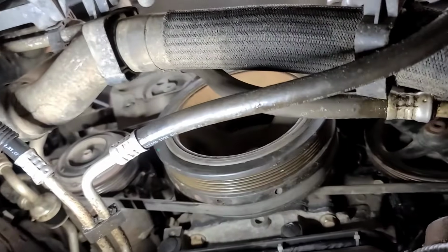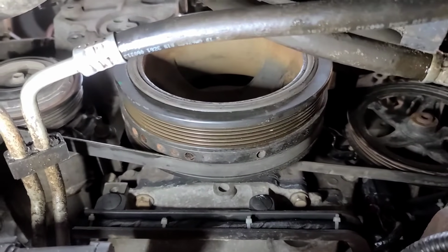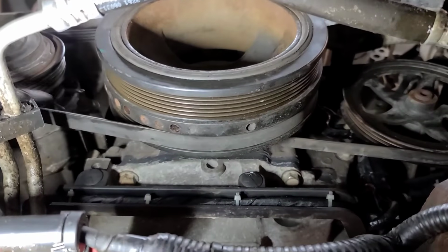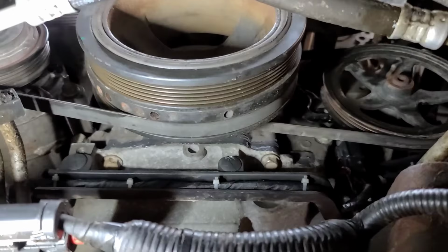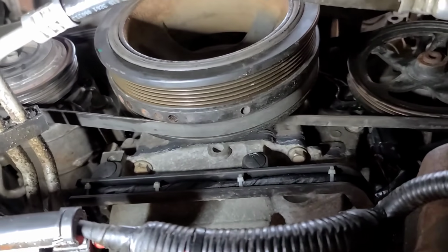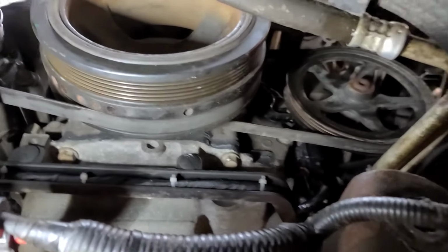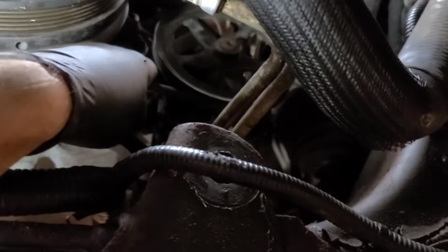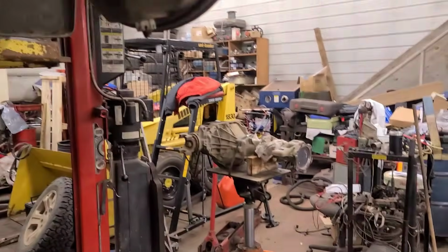So there's the AC compressor back on. Actually, the belt wasn't that hard to put on. Just start it on this side, put it on the main pulley, and turn it clockwise while you work it onto the pulley. Yeah, I had to turn a couple turns to get it into the grooves. Man, those things stretch a lot. But both stretch belts are on. Now we're going to put the front differential in.